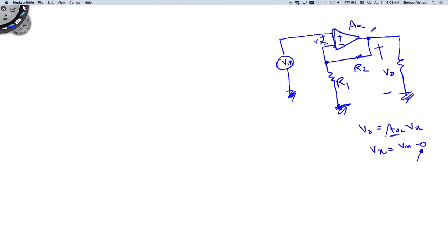R2, if I have a voltage here and a different voltage here, then current will be flowing in this resistor, right? So this R2 will have one voltage here, another voltage here that is less than the voltage that I have at the output, because this output voltage is equal to this voltage plus this voltage, right? Remember, this is a loop, where output voltage is equal to the voltage across R1 plus the voltage across R2, right? So I took part of the output voltage, which is across R2, and fed it back to my amplifier.